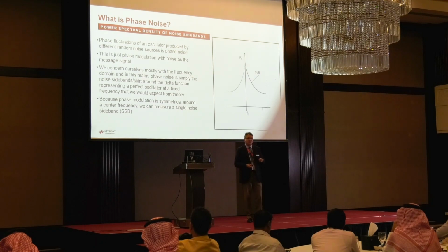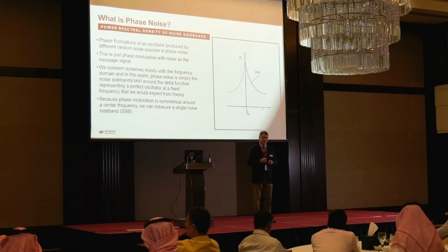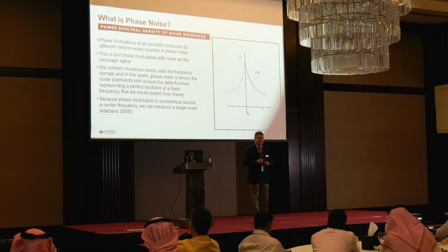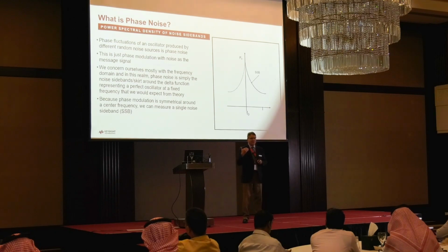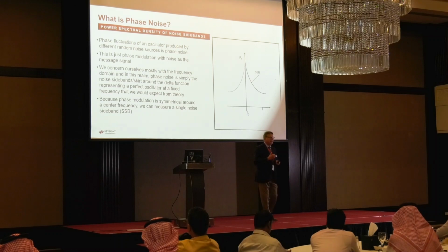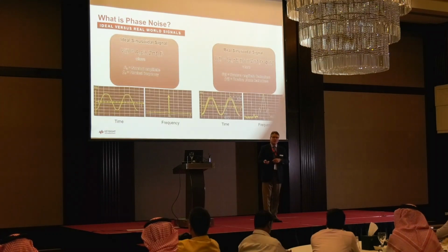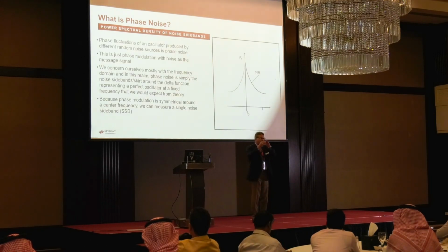So what the phase noise is, is actually a way to talk about the amplitude of that sideband, the SSB, relative to the carrier power, P sub 0. And we'll see in a few slides that in the case of phase noise, or noisy changes, random changes in the phase of the signal, instead of seeing sidebands as shown here behind me, we actually have noise skirts on both the upper and lower side.